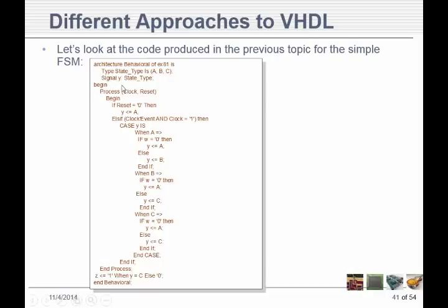The other thing about them that's real nice is they're never defined as an input or an output. They can have data flowing either way on them. So here I've got a signal that I'm calling Y and saying it's of type state type, not standard logic or something like that. It's a state type. So Y is going to only have 3 possible values, A, B, and C.